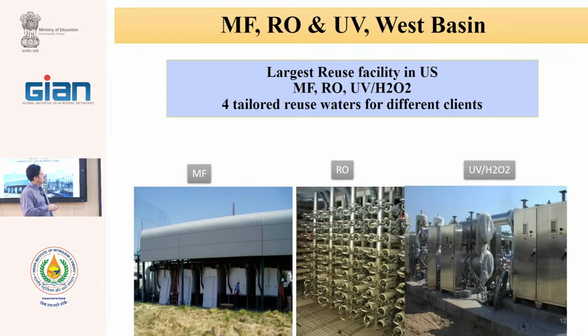Therefore, if you check the internet, you will see that in recent years this coupling is mostly used: hollow fiber MF or UF as a pretreatment of RO, and after RO, UV with H2O2 as disinfection and removal of the organic matters.